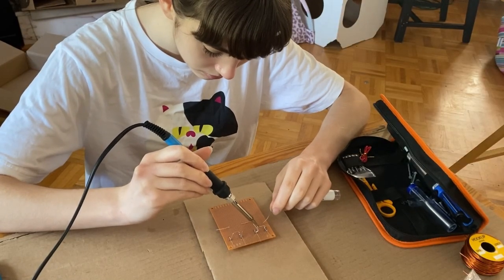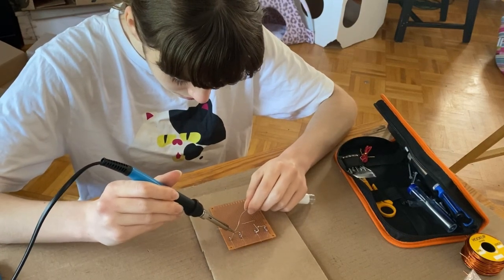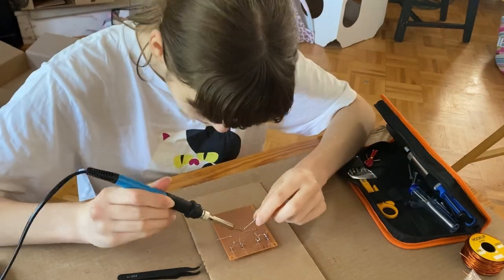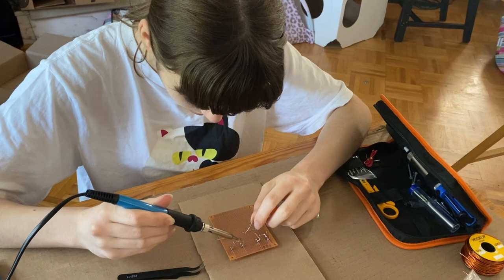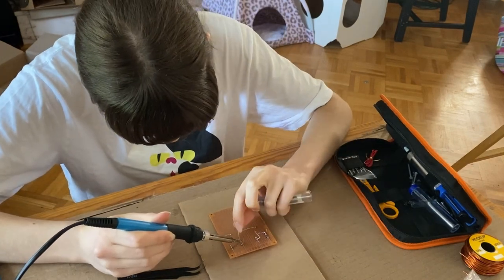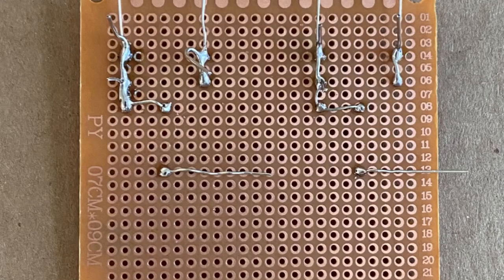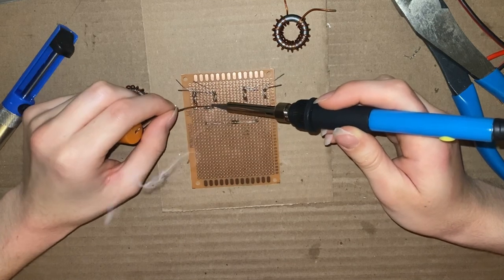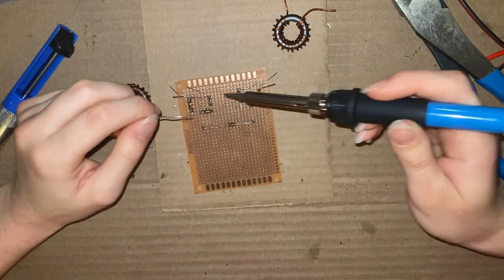Although having to keep flipping the board upside down to solder components and connect them properly kind of threw me off. I realized I made a mistake by soldering each end of the 220 ohm resistor to the positive side of the Zener diode, which would be connected to the source of each MOSFET, and it's supposed to be connected to the gate. I fixed this by desoldering it and then resoldering it to the negative side of the Zener diode so it can be connected to the gate.